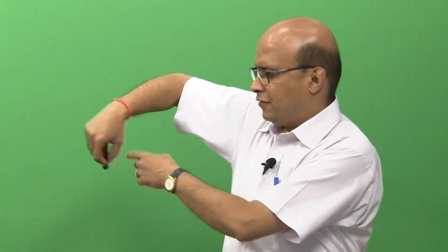Let us look at a very simple example of a two-link manipulator which is going to move. So, let us again take the example. This is my arm, one link here, one link here, and I want to move from here to here in a straight line. Okay. So, essentially this is a point B and this is a straight line A. My arm is like this, if you can imagine, this is L1, this is L2, and I want to move like this. So, if I want to move the end effector with a velocity of 1 meter per second, then what are the corresponding joint velocities we want to find? So, if I simply draw it here, this is the problem that we are trying to solve.